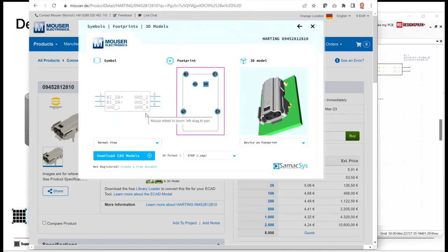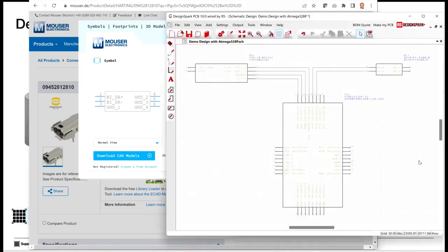However, once you're ready to do a design, and now I'm in the middle of a design here, I'm doing a microcontroller design. This is an Arduino workhorse, the Atmega 328P. Then I have a power supply here from a power supply manufacturer called Traco. I'm using an optocoupler from Vishay, and now I want to use the Ethernet connector, the SPE connector from HARTING, for my communication in my edge environment that I'm designing with.